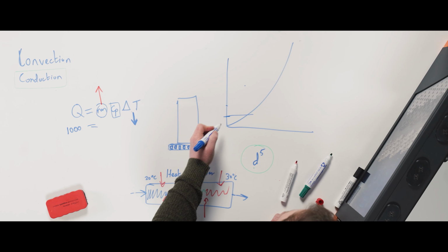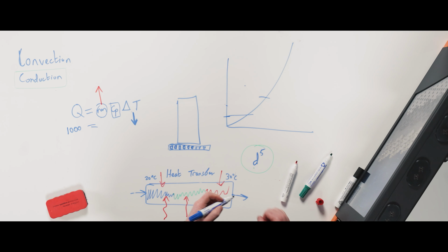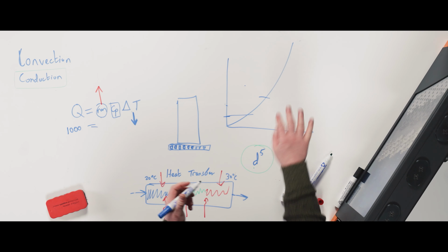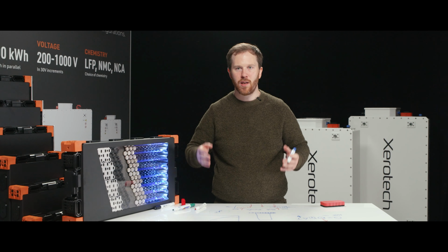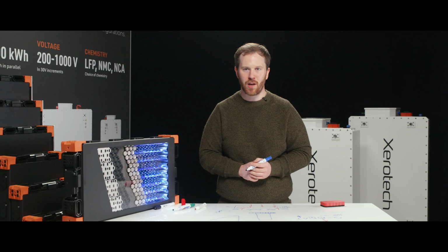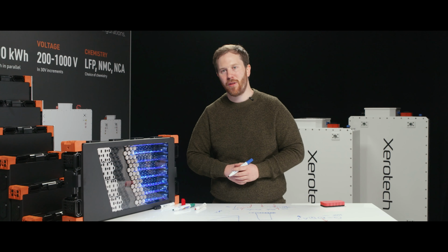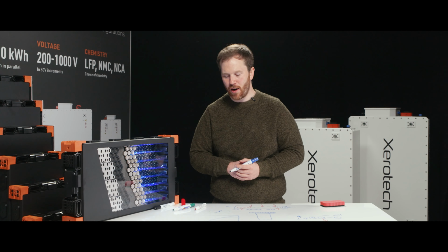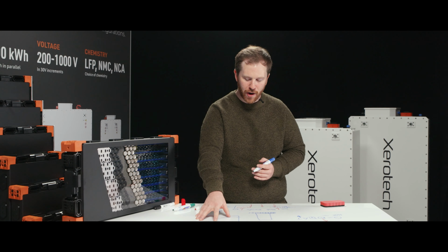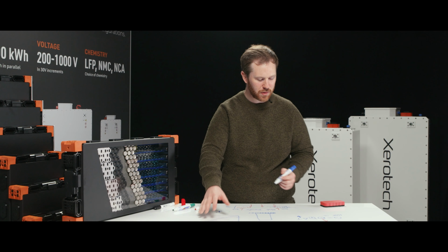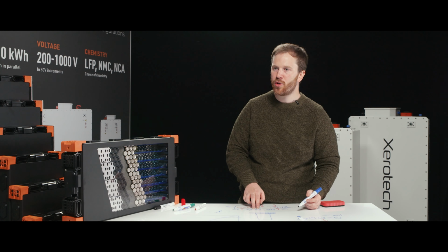The more you pump, the higher the pressure drop, the more energy you need. It becomes exponential. So it's not quite you need twice as much flow rate, you need 4 times as much power. It's even higher than that. It's exponentially higher as you go up. So it's incredibly important to design your systems to have a low pressure drop.